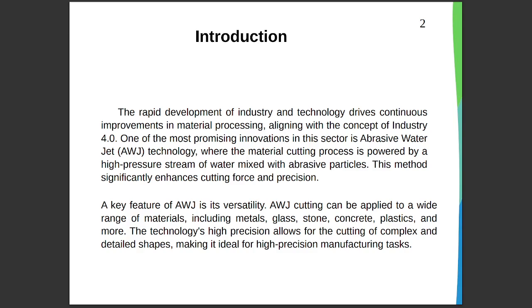The water jet acts as an ideal single-point cutting tool, enabling efficient automation. It can cut any contour with clean edges, allowing it to create shapes in both horizontal and vertical positions. Cutting can start in the middle of a sheet without a pivot hole. Works well with other cutting systems, expanding material range and thickness. Narrow cuts reduce waste and costs. No heat generation prevents rewelding and material degradation. Minimal fire hazards, suitable for explosive environments.